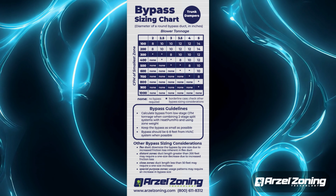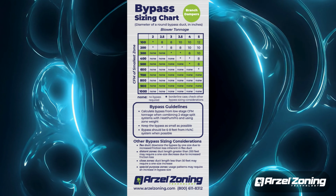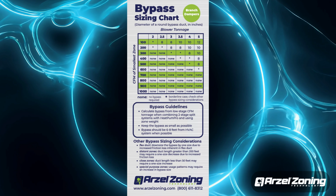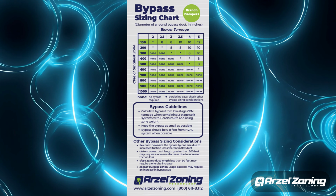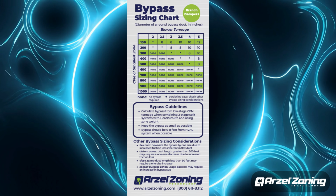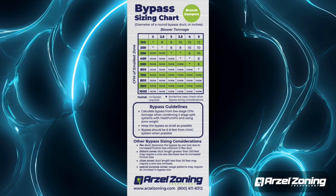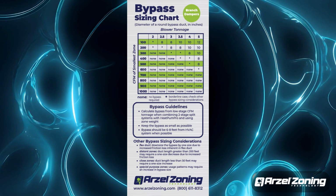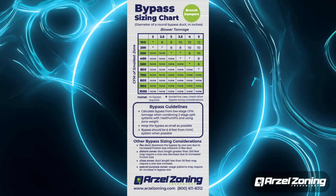Now flip it over and go to the branch damper side. Do the same calculation, 300 CFM, 3-ton system. Branch damper should be the asterisk, which is borderline, which tells you down here, the asterisk borderline case, check other bypass sizing considerations, that's down here. If it's a distant zone, flex zone, you're definitely not going to need one. If it's very short, it's hard metal pipe, and it's the bedroom right above the equipment, you might want to figure one in.